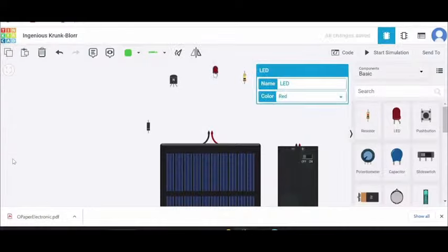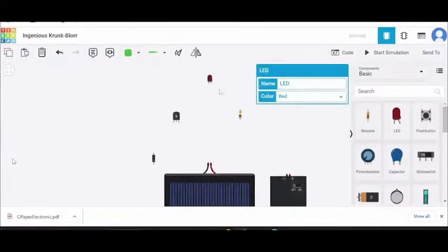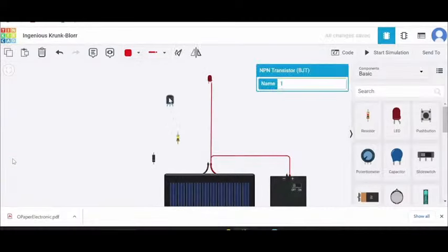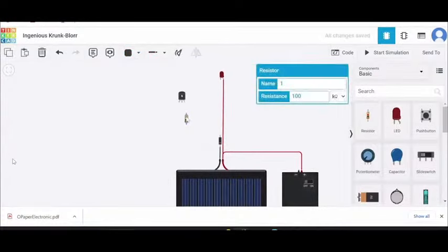So I'm going to connect all these components together. First thing is I'm going to place the components as required. Connect the positive terminal of battery to the positive terminal of LED and solar panel. I'm going to connect the negative terminal of solar panel to the diode. Make sure that the line on the diode, that white line, is towards the negative terminal, that is cathode.